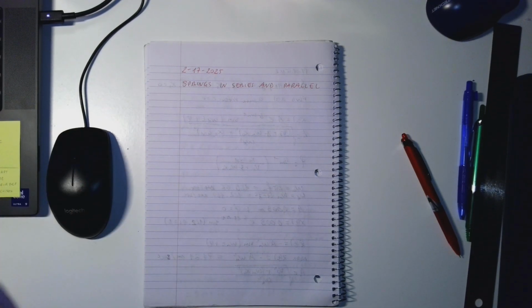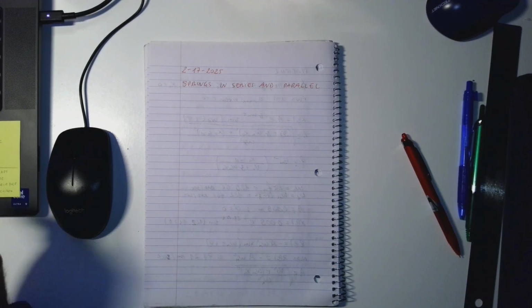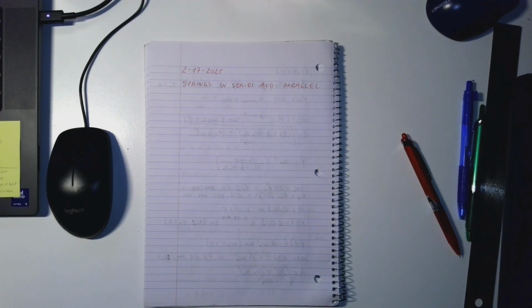In particular, if we have two springs that are in parallel, it means that they are subjected to the same displacement, which could be the same elongation or the same contraction. When we look at springs that are in series, they are actually subjected to the same force, but they can have different